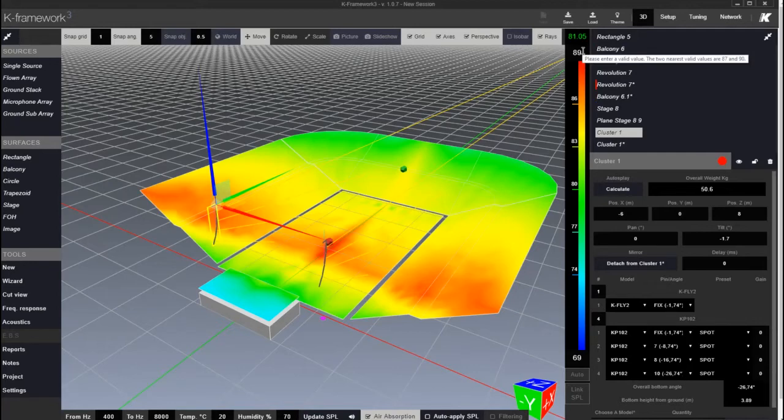The crest factor, these are based on our data sheets. So basically, it's considered with the same ideas, with the same calculation, but that's coming at the end. We will have an adjustment, two modes to work, because we need an adjustment factor here that will reduce a little bit the SPL, to be able to work also with real amplifiers, because this software is directly connected to the DSP of the speakers. And so we need a little bit of margin. But then it's the SPL that you see on the data sheets, and it's the SPL that you will see on an SPL meter on the field.